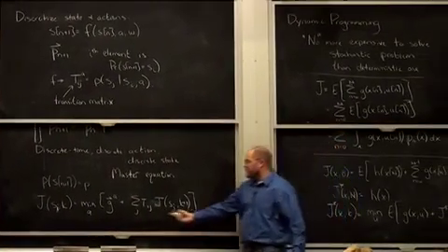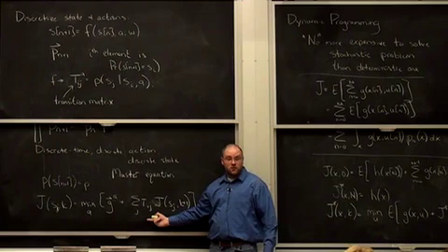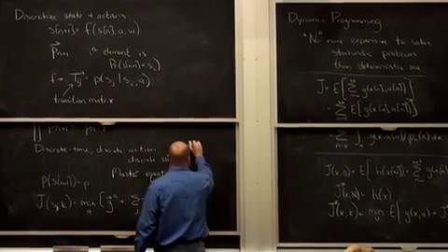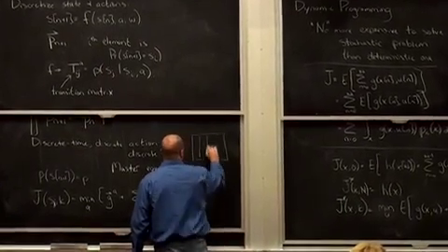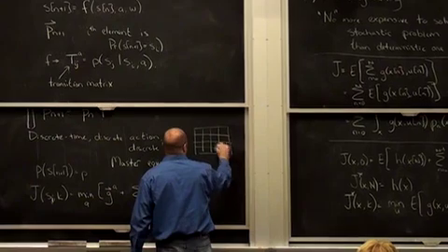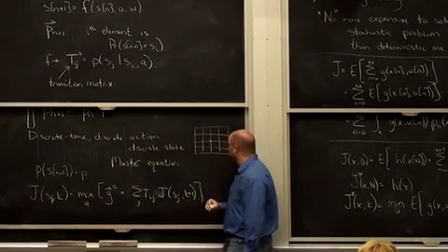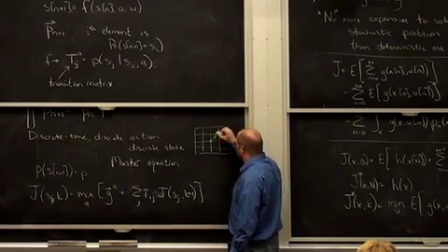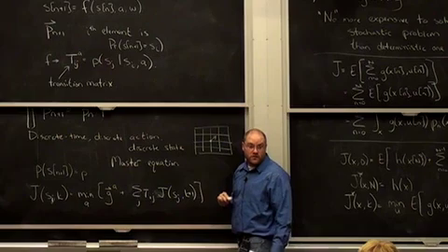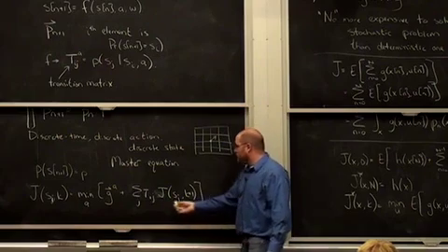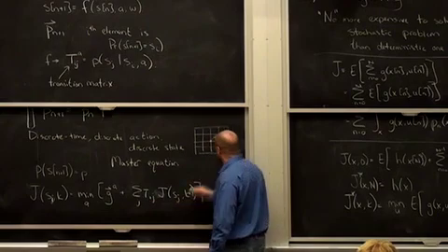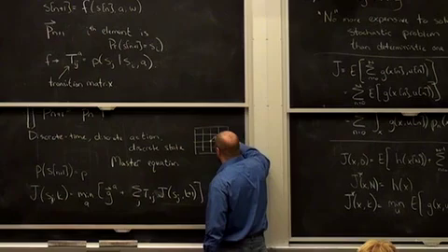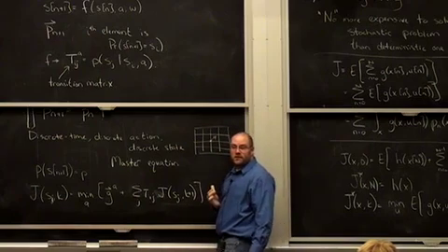We already used this form when we were doing the barycentric interpolation, because our problem in the dynamic programming originally was that when we started simulating from one node forward, unless you were very, very lucky, it didn't end up right on top of another node. So we already said that we're going to estimate the new cost to go as an interpolation of the value at the neighboring points, where that weighting came from the barycentric interpolators.